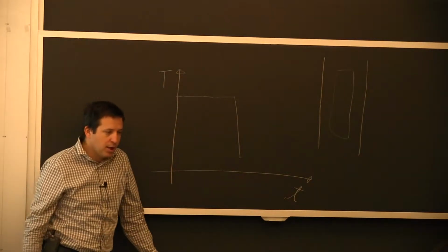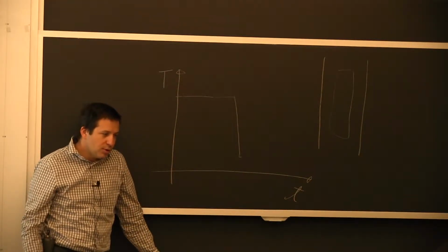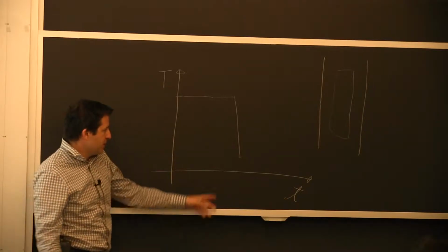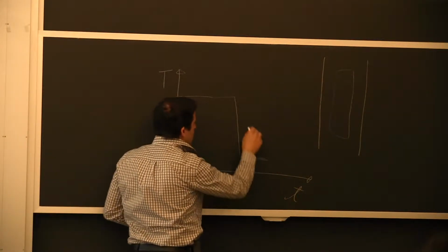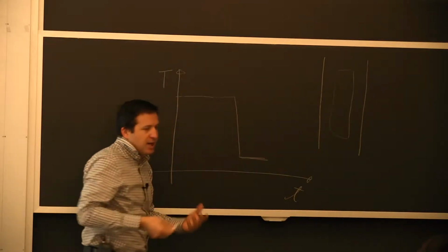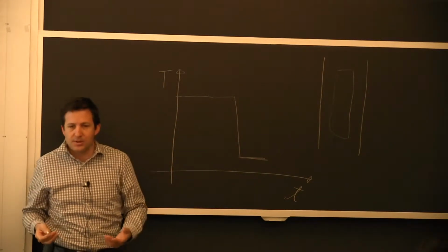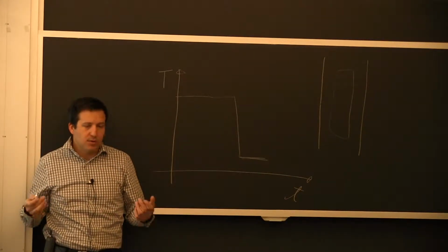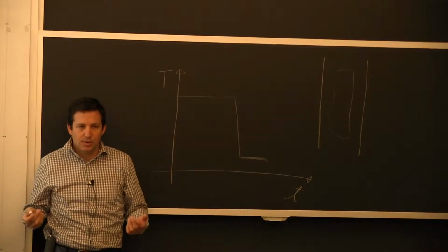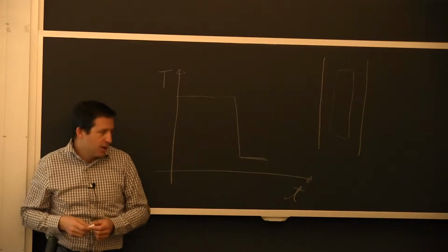Now, you could use the alloy as is in this quench condition, but it's normally very soft because you quenched, you didn't have the time to form the precipitates. What do the precipitates do? They increase your yield strength. They are obstacles to dislocations in aluminum.